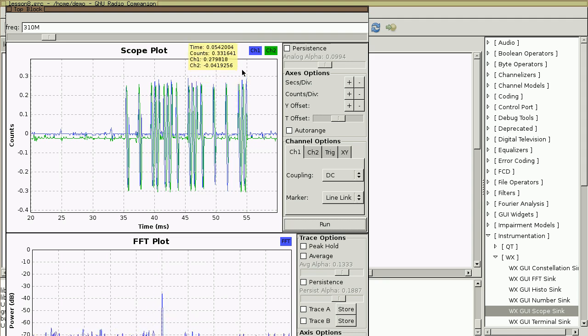And one of the things I notice about this is that this pattern, short, short, long, long, short, long, short, short, short, long, is the same pattern that I have the dip switches set to in the garage door opener remote. They're set to 0011010001. And actually there are 2 more dip switches, but we seem to be only using the first 10 here. The first 10 dip switches correspond exactly to this pattern of short and long pulses.